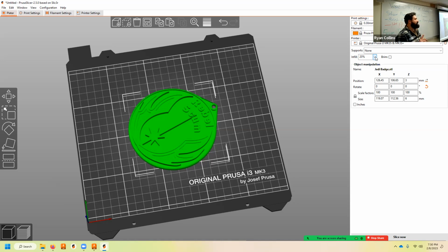For FDM filament printers, you are creating an object. It prints the shell, the outside is the detail that it's focusing on. The internal space, the internal mass, the internal volume, it creates a patterned infill. It takes up the space. Through your choice of pattern, it creates a pattern inside that helps support the whole thing. The infill percentage is how dense or how sparse that is.